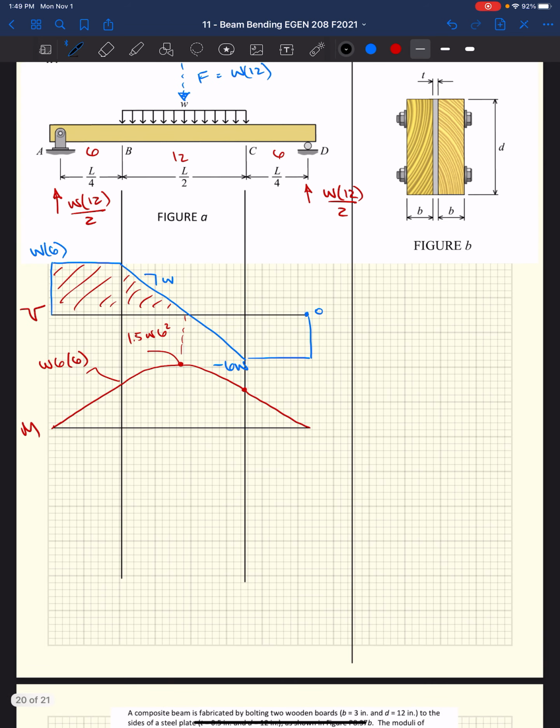All right. So now that we have our internal forces figured out, we figured out M. We need to know what I is, Y is, and this modulus ratio. Well, modulus ratio is what we really need to know first. E original, E reference. I'm going to change steel, which is my original, into wood, which is 30,000 over 1,800, 16.67 is our modulus ratio.